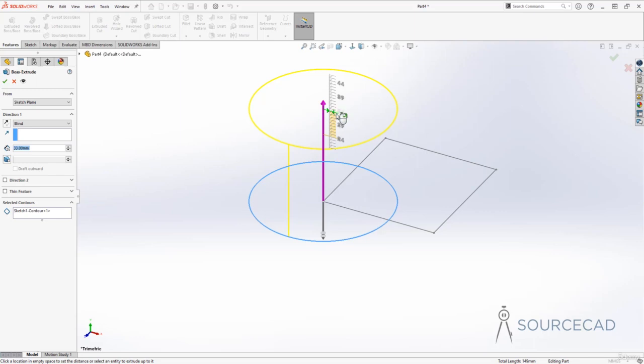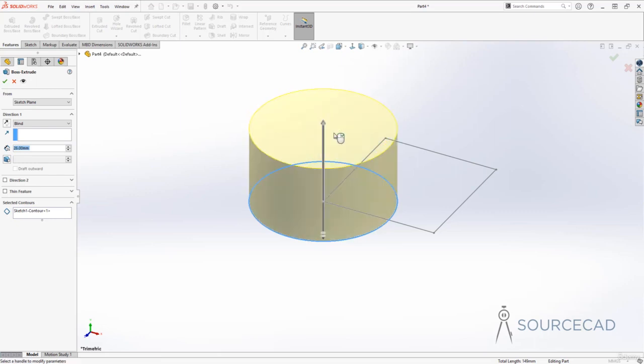When you move it further away, it will let you again extrude by a factor of 5, 10 depending on the size of your extrusion. So in this case, I'll just leave it like this. So this height currently is 26 mm, as you can see here in the properties manager. Now let's change it to a specific value like 20 and I'll press the tab key and this will change here as well.